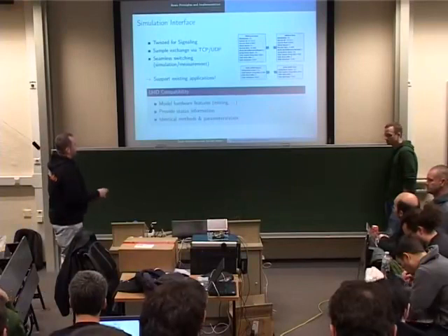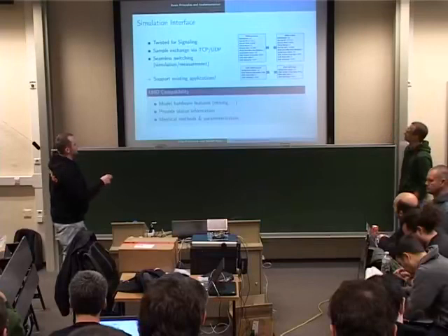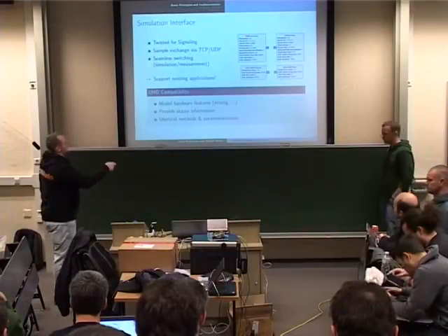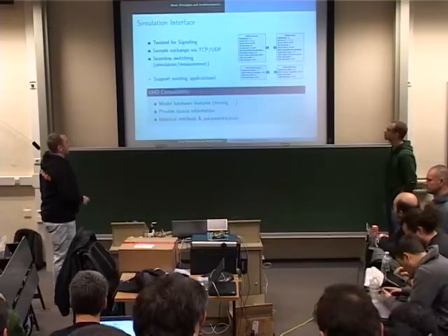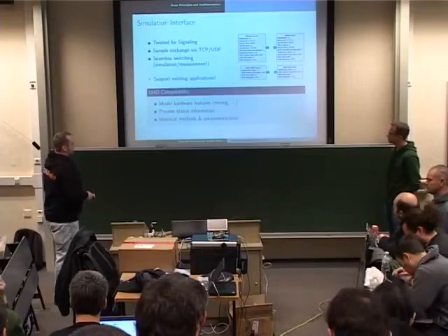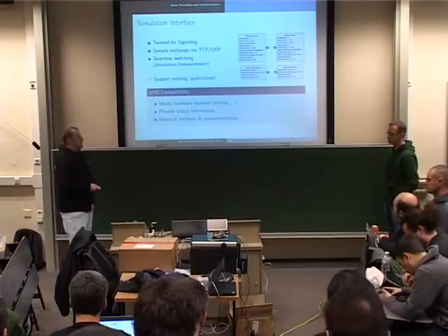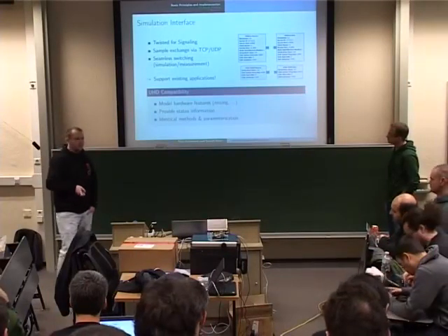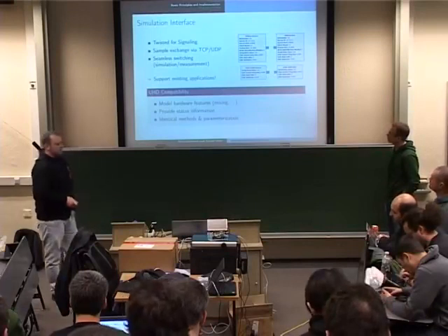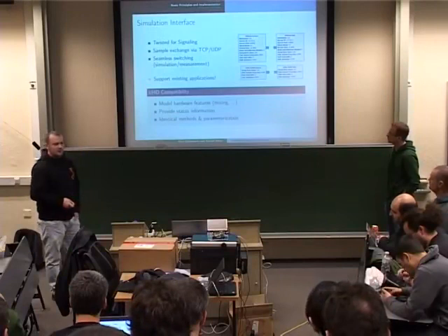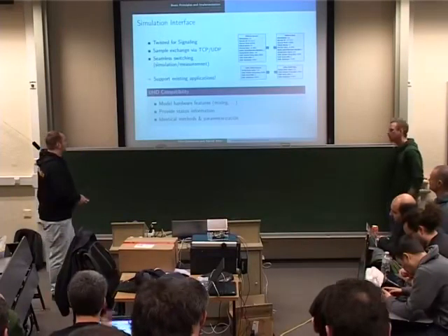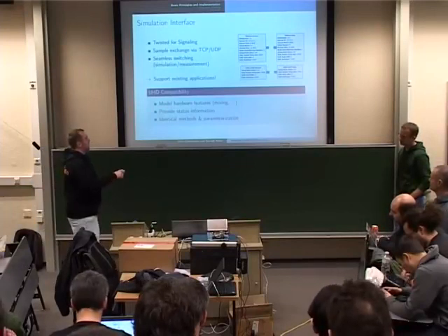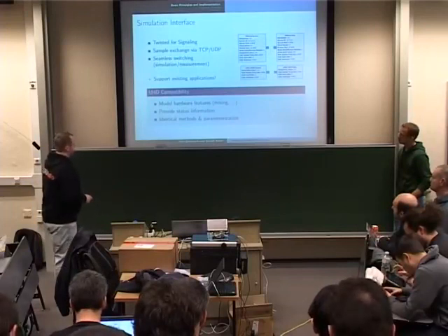And as you can see here, the switching is really seamless. The blocks have the same options, because I copy pasted them from the UHD blocks and added some of the simulation parameters to them. So there's support for existing applications. In my master's thesis I wanted to show the performance of the overall system with some PER and BER curves, and therefore I used the standard TX benchmark and RX, which are part of the GR digital package, and it worked out of the box. I simply took out the UHD block and added a Wireless source block, and it worked out of the box.